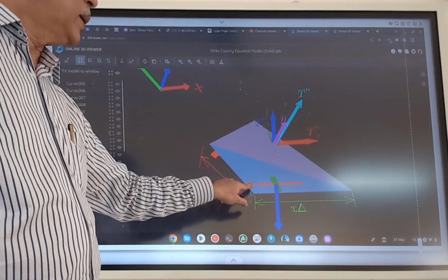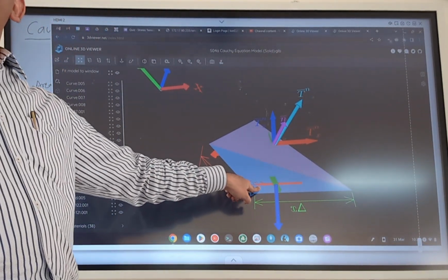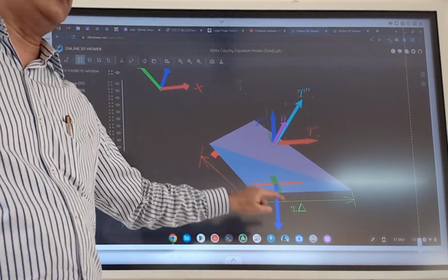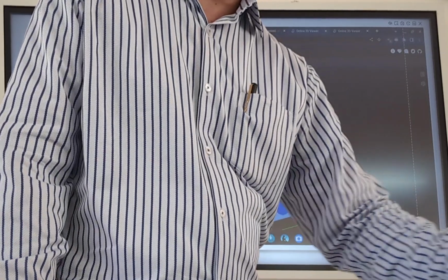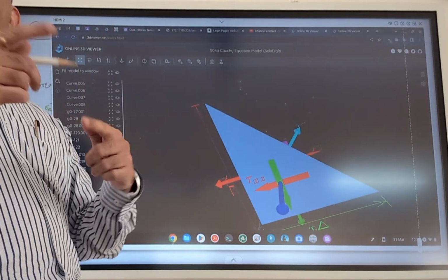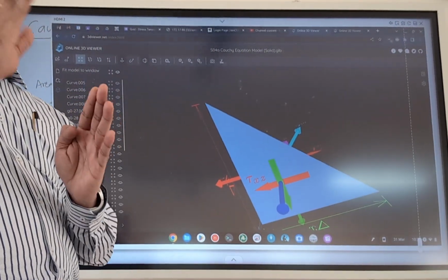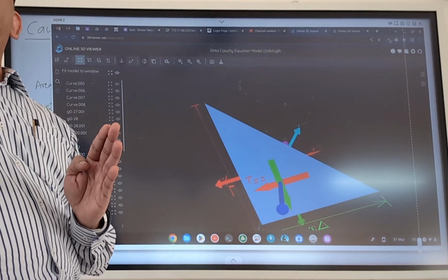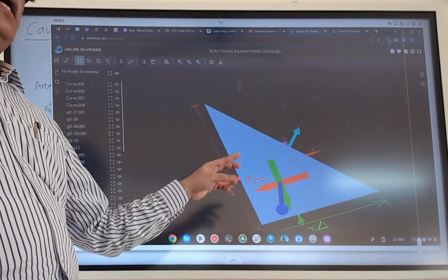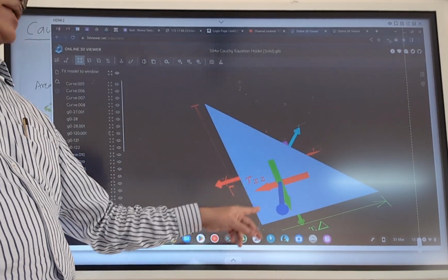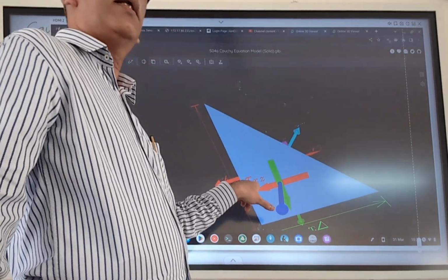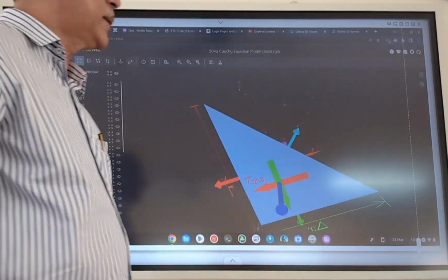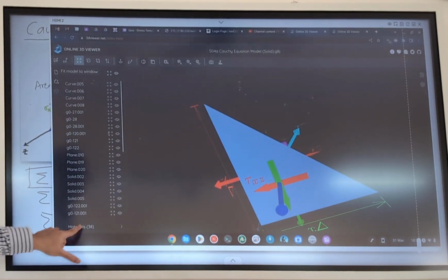So what will you designate this stress as? It is tau zx. So that is what is written. I have written here xz just to maintain, in this course we will be writing sorted by the coordinates. So x, y, z. So yz will be yz, zy will be again yz, and xz, zx will be written as xz. So this is the xz component which is opposing this Tnx component.